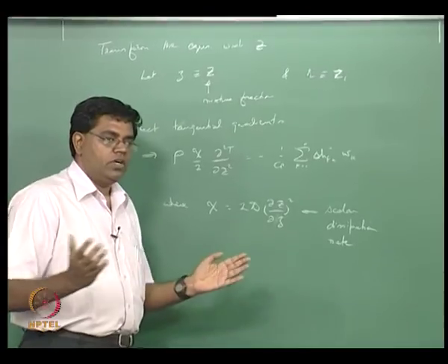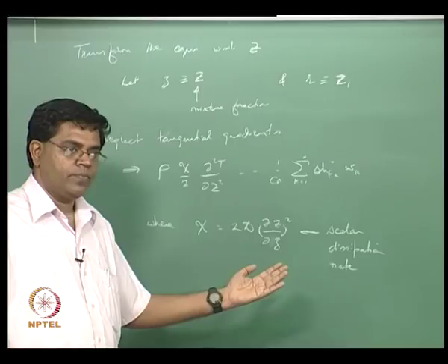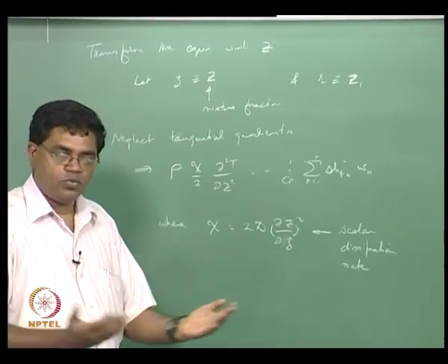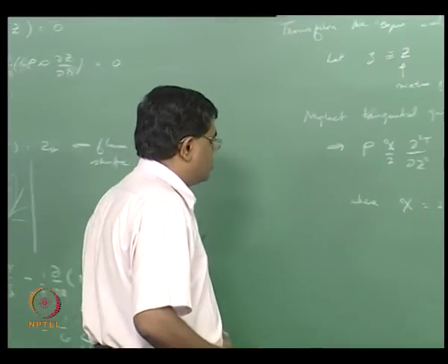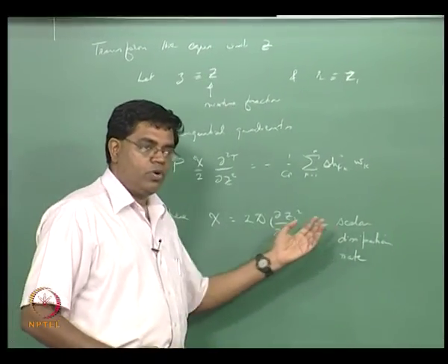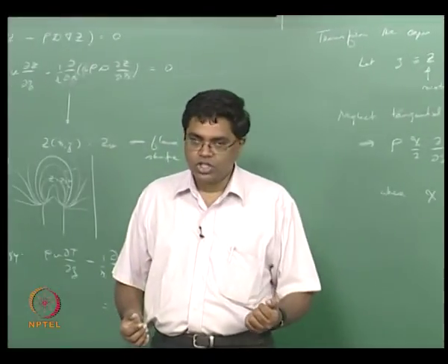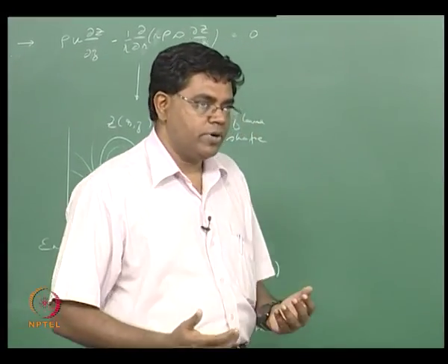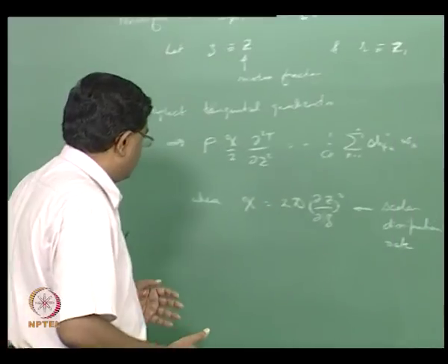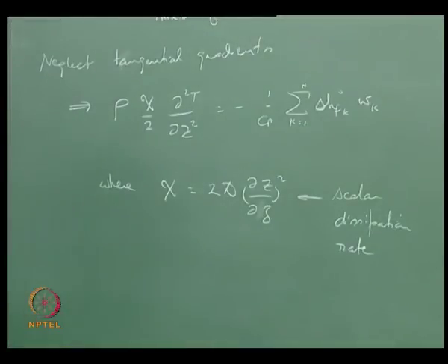Okay. How the mixture fraction variable is now going to decay because of diffusion, while the mixing happens between fuel and oxidizer. And this is actually quite important in turbulent diffusion, wherever you are looking at, for example, scalar transport by turbulence. Then you have the turbulent diffusion, mass diffusion coming into the picture, and the scalar dissipation rate under turbulent conditions would be quite an important quantity there, but at the moment let's not worry about all those things.